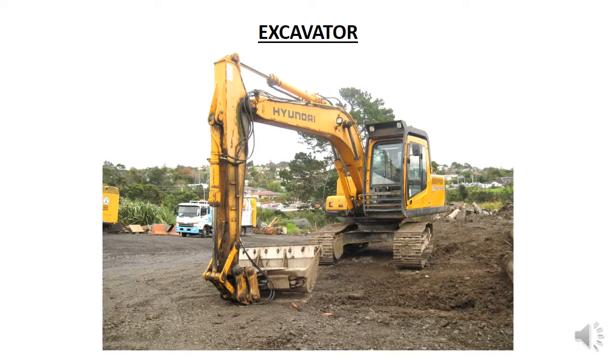The operator sits in a cab beside the engine. The cab is located to provide a good view in front of the excavator, but note that the operator's visibility is blocked by the boom on one side and the engine at the back, which is a significant safety risk.